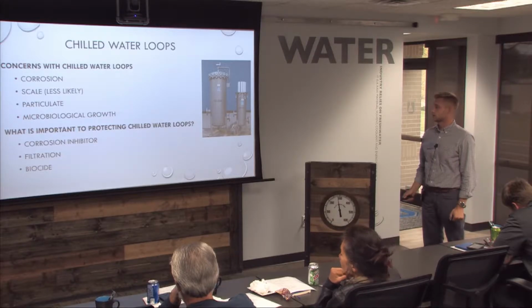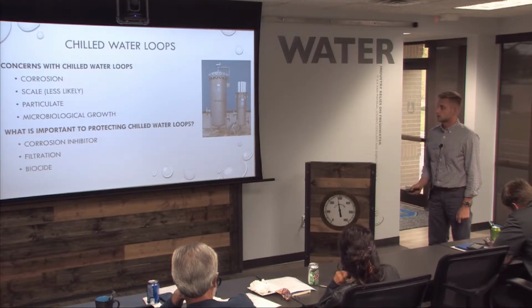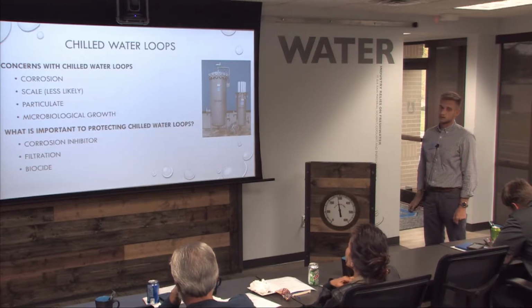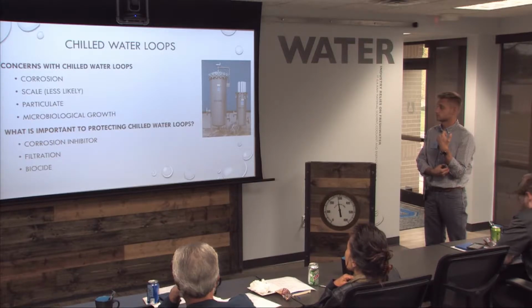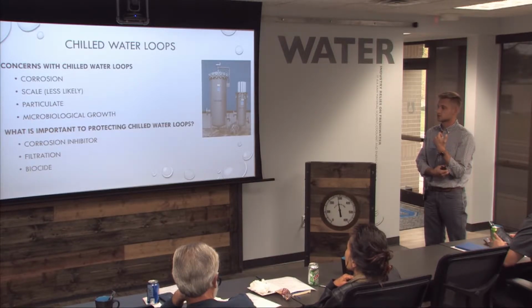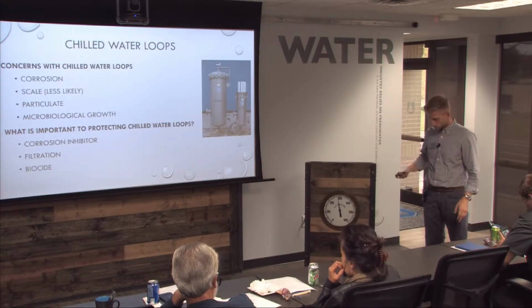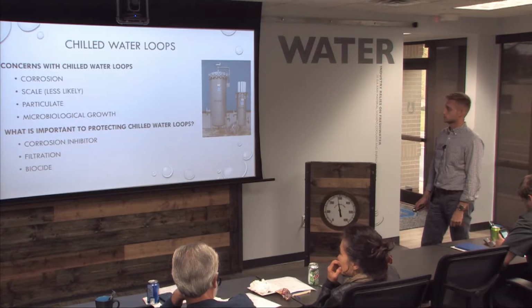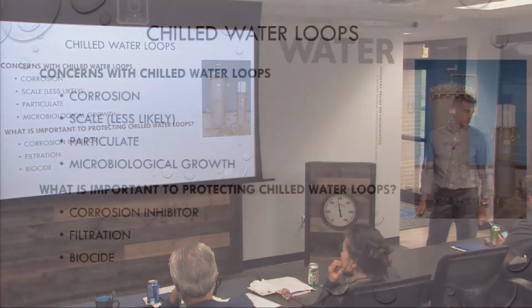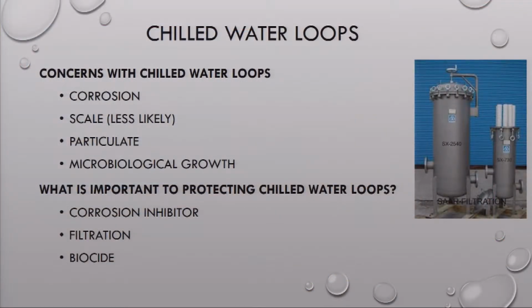If you have a ton of sediment, you're going to have major corrosion problems. And then typically we feed a biocide only when we run some biological counts and we find that it's higher than normal. But it's those weird temperatures like 60 to 100 degrees that cause your biological problems. So typically hot water boilers, not an issue, or really cold water systems, also not a major issue.